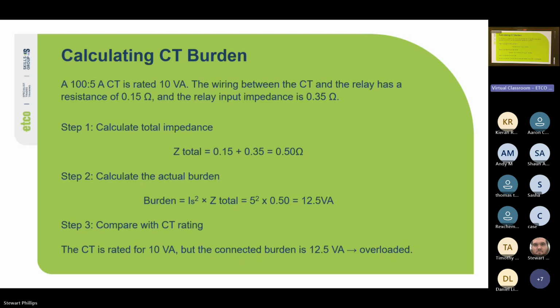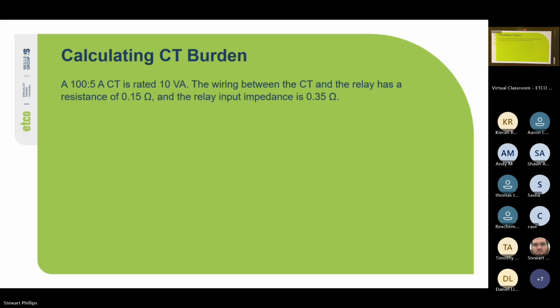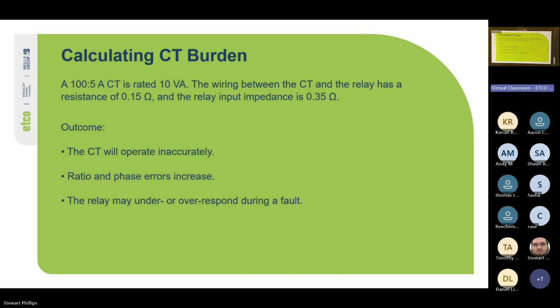So the consequences of this: the CT will operate inaccurately. The ratio and phase errors will increase. The relay may under or over respond during a fault. And in severe cases, the CT core could overheat or saturate during normal load.